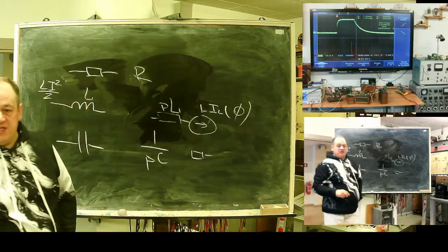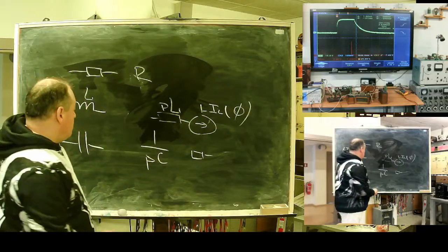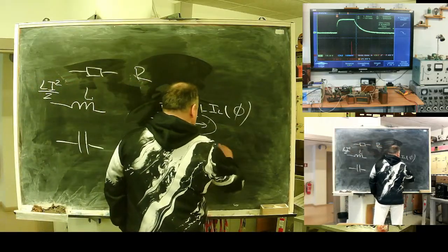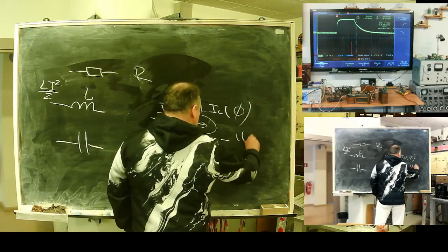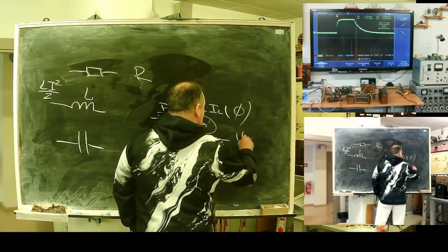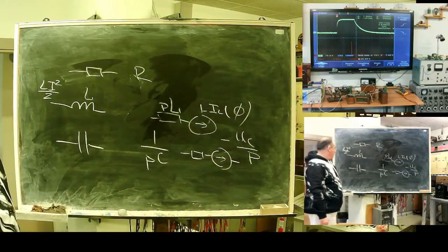What means current of 0? The current at the moment of computation. For capacitors, you add minus capacitor voltage divided by complex frequency.